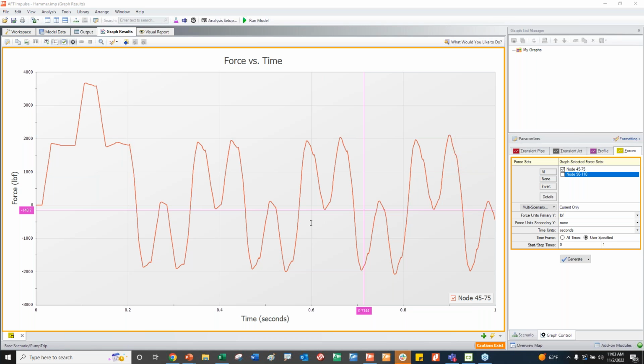How can this be used for a crossing? I imagine by crossing you're talking about a change in direction in a pipeline when you cross a road or something. Well, in the same way, in the crossing you have elbows. You can calculate the imbalance forces there and determine whether or not the forces are too high, and whether you need to use restraints or directional anchors to control the high forces generated in the crossing.